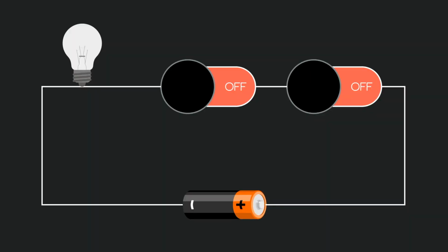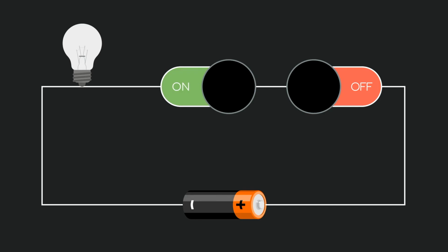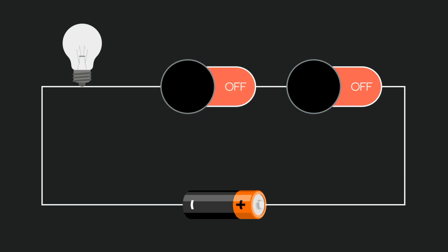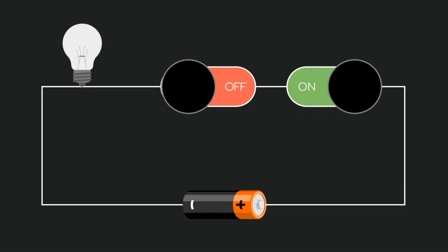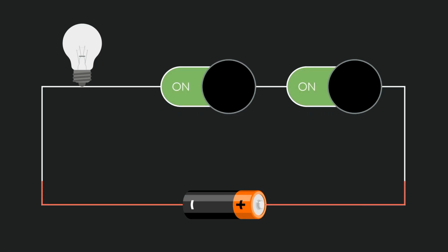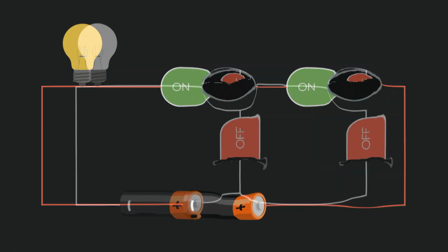For example, let's put two switches connected, one after another. Now, if we only turn on a single switch, the electrical circuit connection with the light bulb is not formed. In order to turn on the light bulb, we must turn on switch 1 and switch 2. We will refer to this as the AND function, since switch 1 and switch 2 have to be closed for the light bulb to be illuminated.